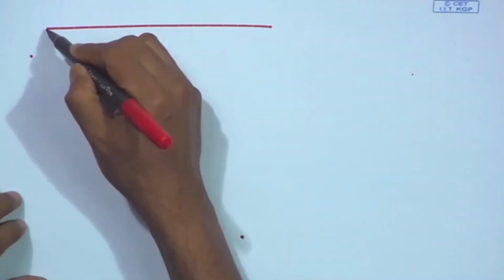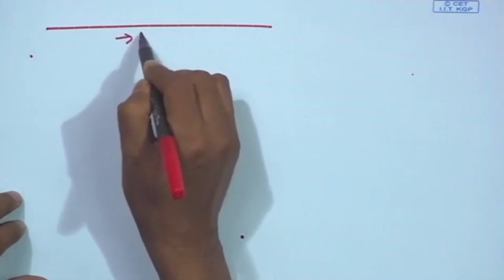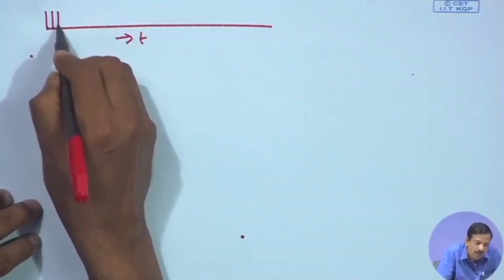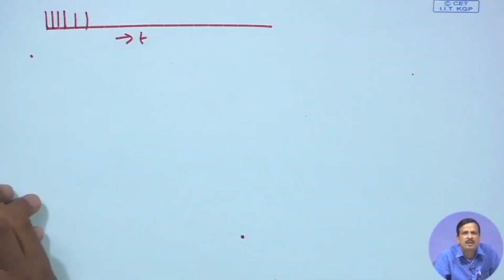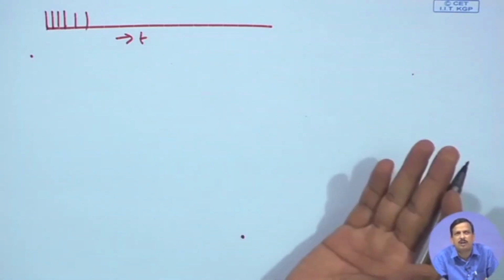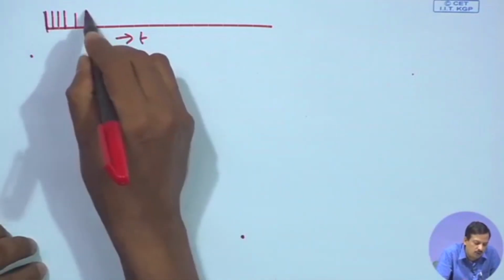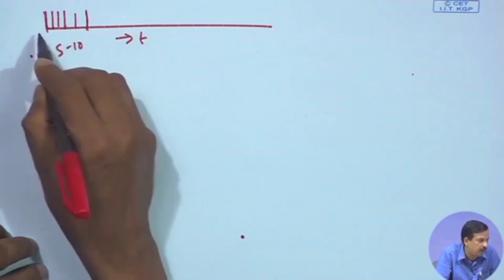Now, if you see, speech is a time-variant signal. So, along the time the speech signal changes its color. If I want to increase the time resolution, I should analyze the signal for every sample, but that analysis does not provide me any information. So, what I want is a small window, let us say 5 to 10 millisecond, if I shift it.